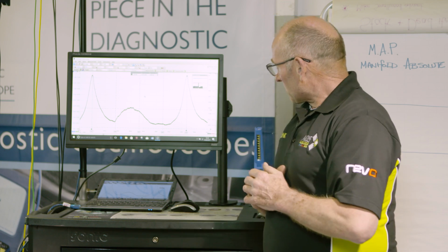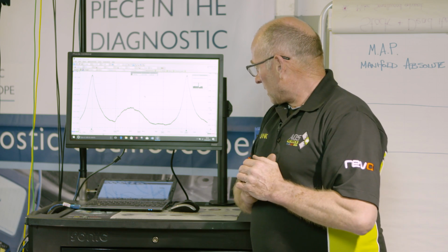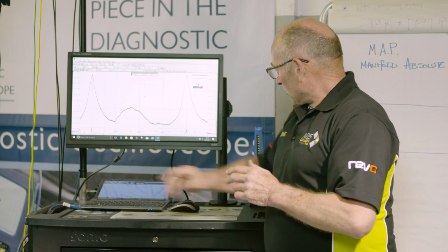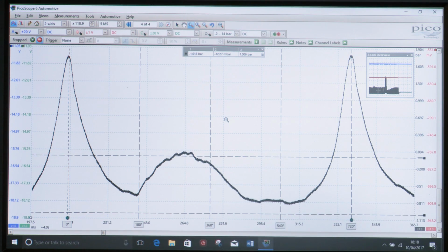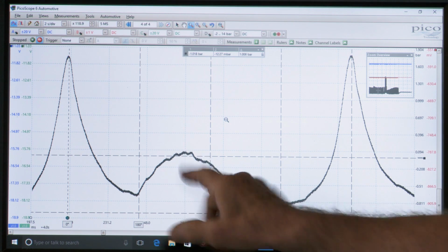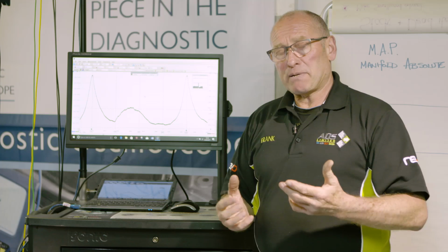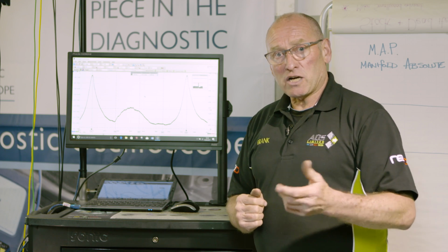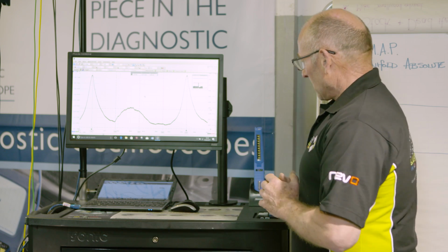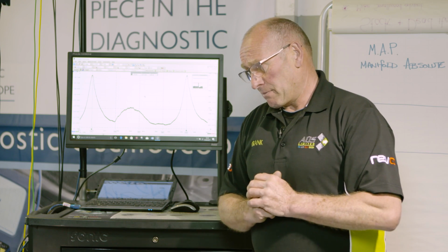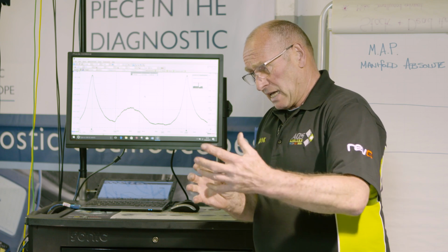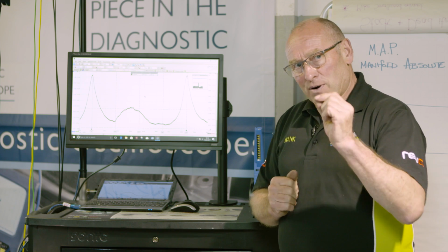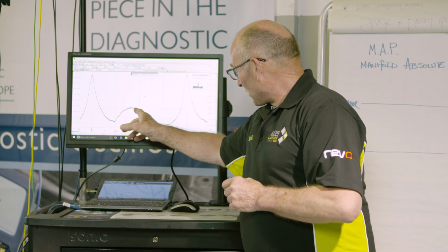What they do is allow the incoming fresh air, clean air charge, which is this bit, to draw in and contain some of the exhaust gases. So by opening the valve early, it actually retains about 10% of the exhaust gases to help NOx reduction without the use of EGR, which is, in my opinion, a really good idea. But this is variable. This has got a variable intake valve angle control under the influence of the ECU. And this is the problem I have. I know what's going on here.